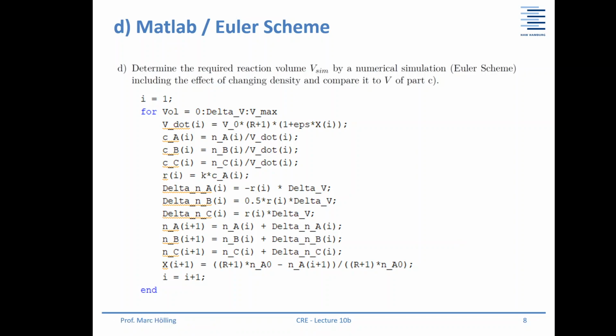So basically this is the numerical calculation for a simple plug flow reactor, and the only thing that we have to look at is this correction here for the volume flow. So in this approach, your inlet volume flow is corrected by R plus 1. This is one special thing, and our conversion here is also corrected with the recycle ratio.